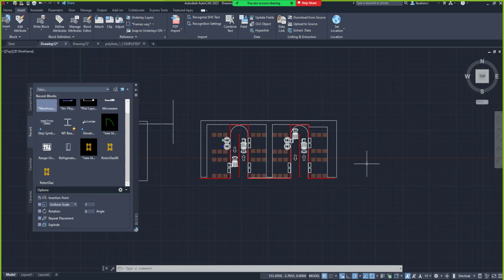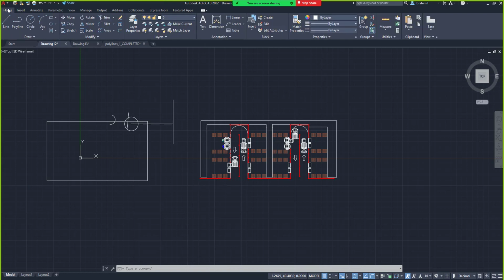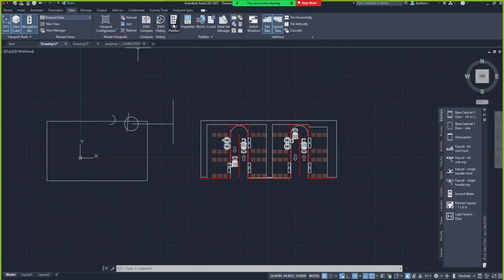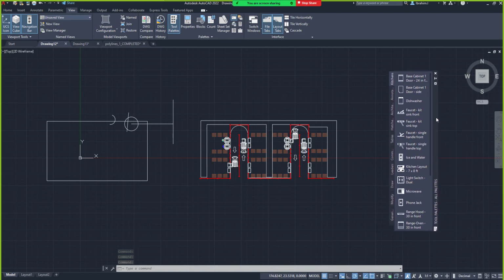That is that about blocks, using block and creating block. Alright, the next thing apart from blocks is that Autodesk has created some blocks for you. Autodesk does not want you to suffer, so they have some blocks created for you. Under the view part, we have something called the tools palette. And this tool palette that we have here, that was where I explained something about the software. We have it for AutoCAD and other software.